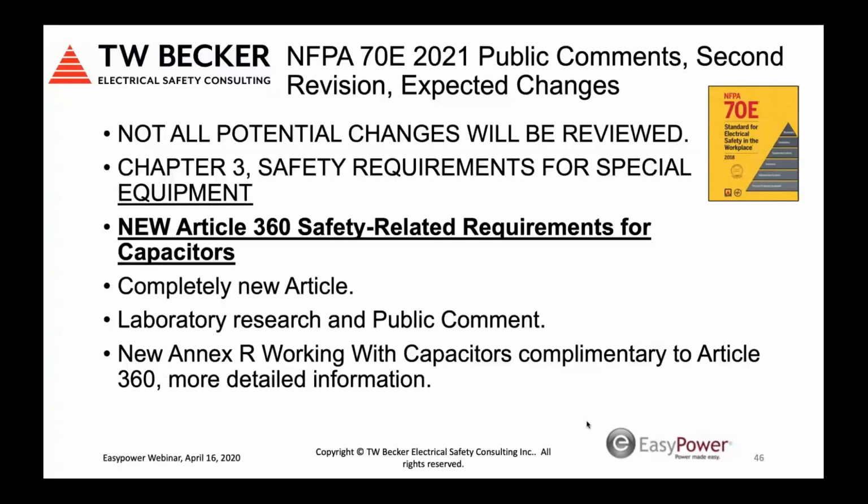And then here I said earlier, this is really the game changer and it's really valuable globally. Again, I keep seeing things come out from our review of these hazards in North America and specifically the US. So we have a new Article 360, which will be anticipated to be a new Clause 4.3 item in Z462, a completely new article, laboratory research and public comment, as I said, and this material was presented at the IEEE Electrical Safety Workshop a couple years ago. And the new Annex R then expands and embellishes on it.